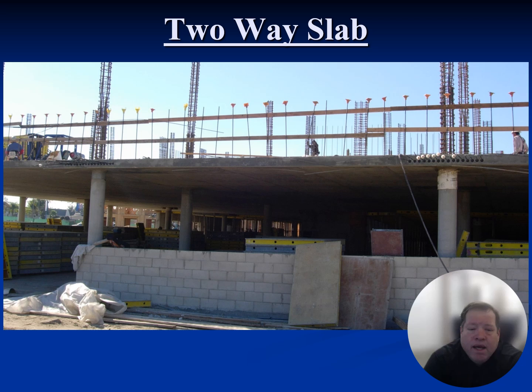If you were to make this a steel structure going 30 feet, most likely you'd have an 18 by 35 minimum girder. You have a 6-inch floor of concrete and metal deck. Right there is 2 feet. We're at 8 inches. We beat it by a factor of 3. We win the thickness of material contest, hands down.